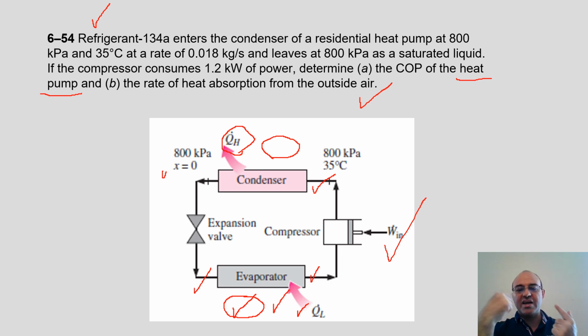So the condenser and evaporator remain the same, but since the direction of the refrigerant changes, their functions switch in the winter and in the summer. Physically, we don't have to turn the device. By changing the direction of the flow, the functionality of the condenser and evaporator switches as we turn the valve on or off.